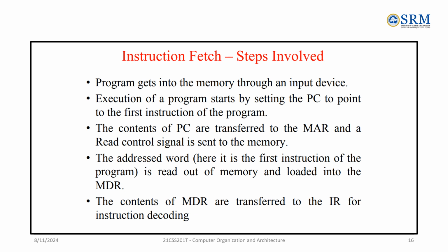Once the starting address is in the program counter, it sends this address to the MAR. MAR is our memory address register. Using this, the memory address register initiates a read control signal. Once the read control signal is initiated, the addressed word is read out from the memory and loaded into the MDR. The contents of the MDR are then transferred to the instruction register for instruction decoding.